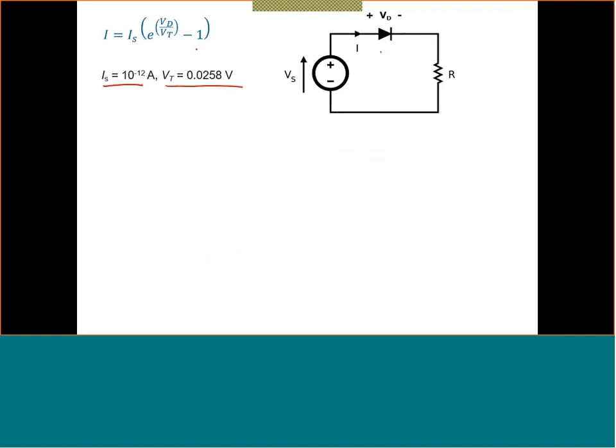However, you will see that a diode can be, this is the real diode. This is the real diode characteristics. Now you will start talking about when you study the diode as an ideal diode. So the ideal diode can have two different models. The first model of the diode: the diode can be treated as a short circuit. So this is the first model of the diode.